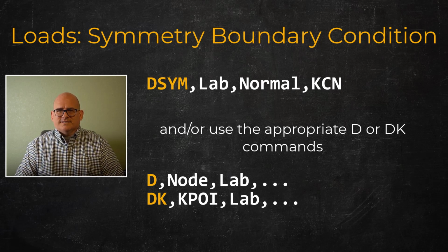In a thermal analysis, however, surfaces with no applied loads or boundary conditions defined are treated as adiabatic, perfectly insulating. The adiabatic condition happens to be the same as the symmetry condition, so in heat transfer or acoustic analyses, no extra step is needed for nodes lying on symmetry planes. We will exploit this later in the workshop example.